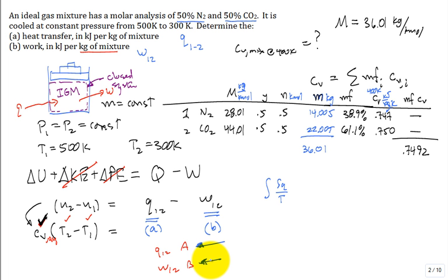From very first principles, I can get the work. Integral F dx from mechanics. When we moved over here, we modified it with an area over area, and we got force per unit area, pressure. Displacement times area, volume change. The boundary work is the integral P dV.